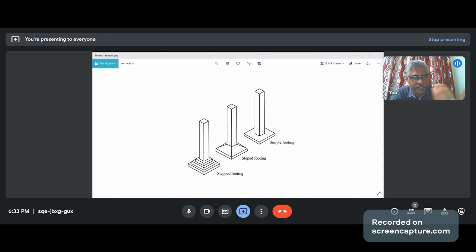The sheared surface will be like the periphery of a box, an open rectangular box or an open square box. And one-way shear is when the slab or footing pad is separated into two pieces. So shear design criteria is very important in design of footing.